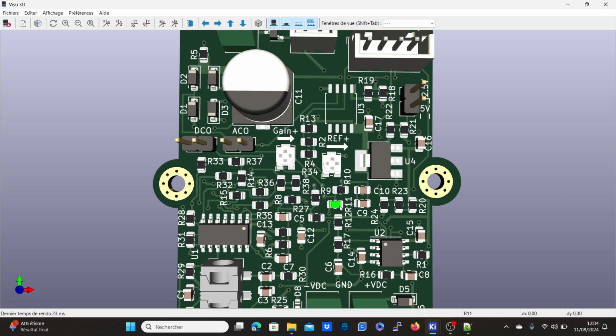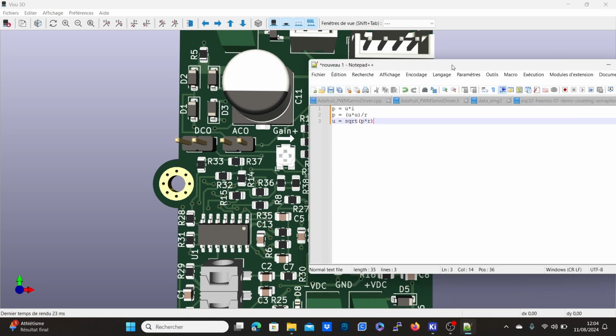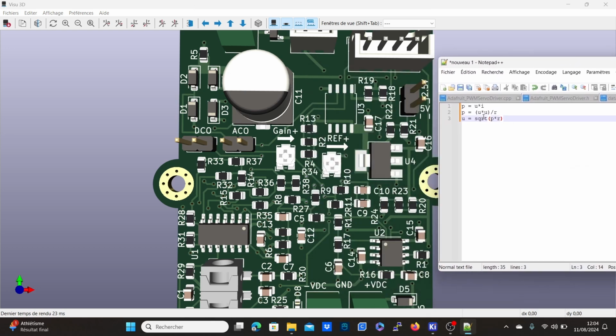One of the questions that I also had when I started was the package for my SMD components. Obviously, one of the constraints is space on your PCB, if you have space constraints. But besides that, can you choose any package for any situation? And no, especially with resistors. It really depends on the power rating of the resistor.